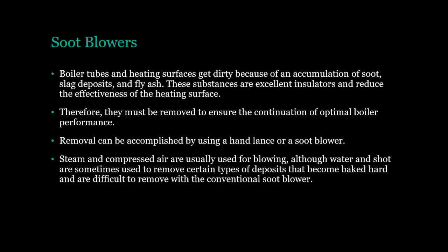Soot blowers. Boiler tubes and heating surfaces get dirty because of an accumulation of soot, slag deposits, and fly ash. These substances are excellent insulators and reduce the effectiveness of the heating surface. Therefore, they must be removed to ensure the continuation of optimal boiler performance.